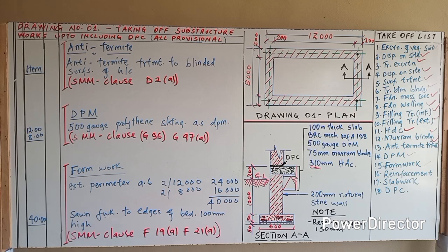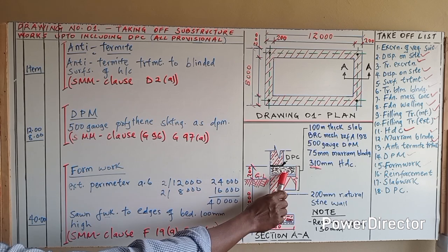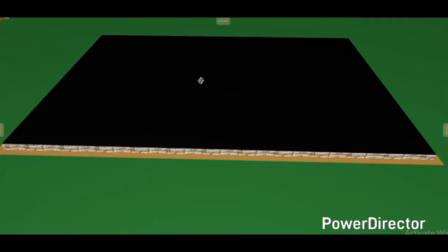So watch the following demonstration how the formwork is being done to the edges of the structure before pouring in this in situ concrete. Now let us have a formwork all around this edge now, so that when we pour our in situ concrete, remember it is wet, it won't spill over.